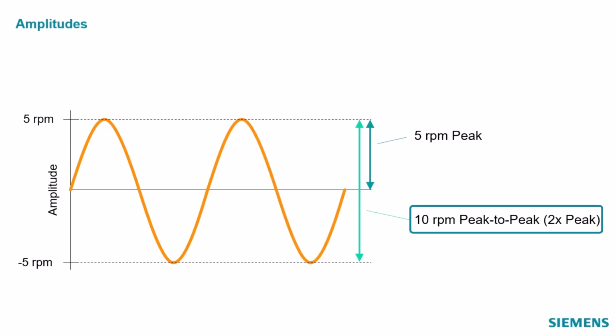When people talk about torsional vibration, it's probably a good idea to know if they're talking about peak or peak to peak. Wouldn't you agree with that, Charles? Oh yeah, that seems like that can make a difference on the target. And yeah, a lot of times the convention is to talk about the peak to peak excursion. But be sure you know when people are talking about the RPM fluctuation, whether they're talking about peak or peak to peak.